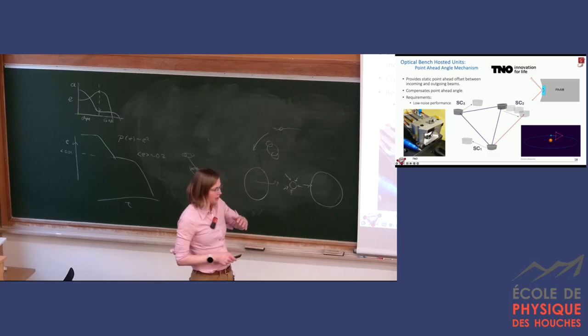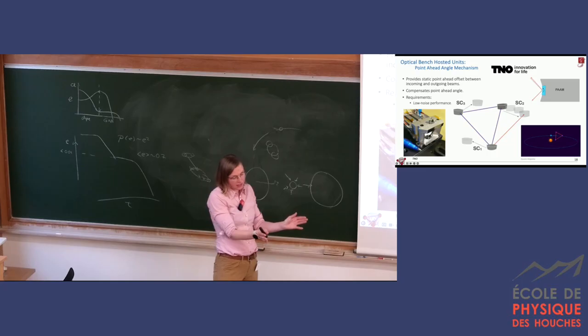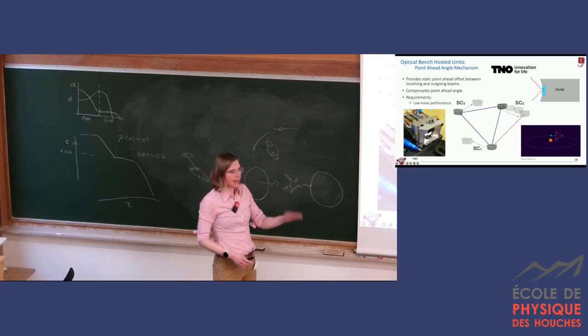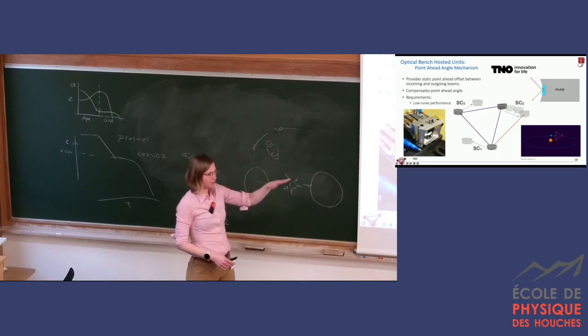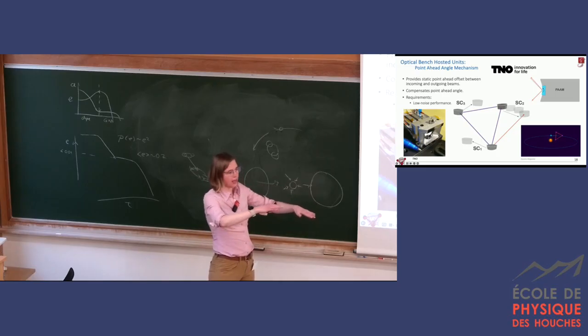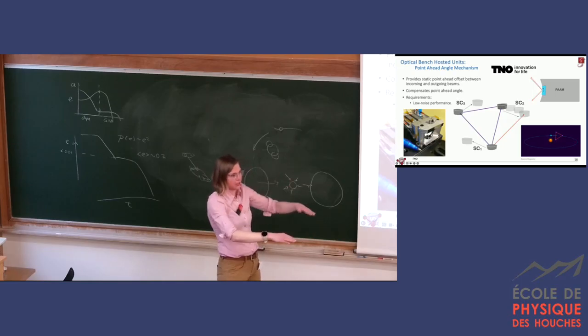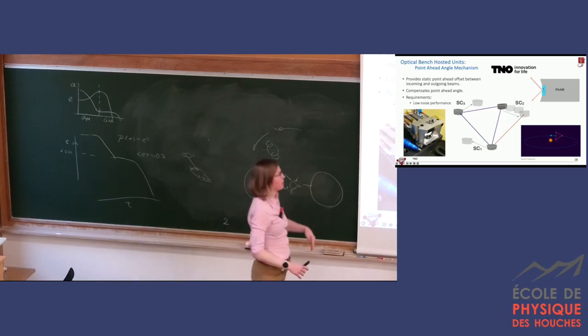PAM is a one-dimensional moving mirror, so it has this rotatable axis. On one hand, it just statically points to the far spacecraft, but it also allows us to point the beam if the spacecraft, due to any orbital effects, get out of plane. So we have to account for that, it can also move in the third dimension.